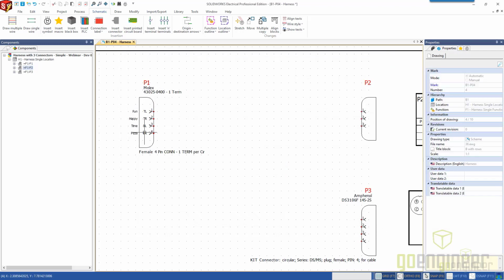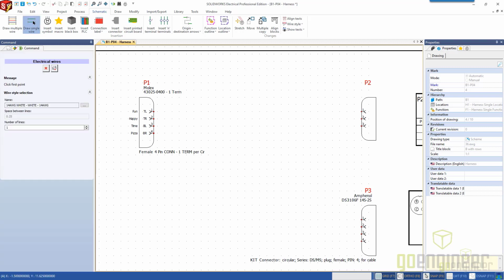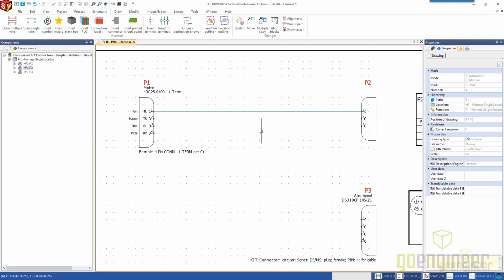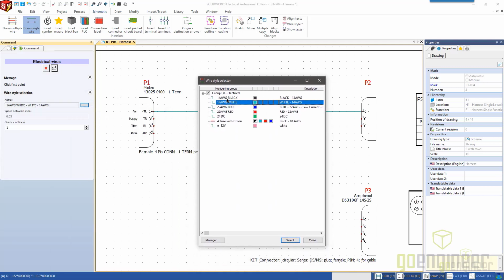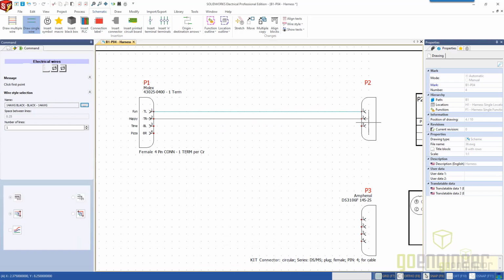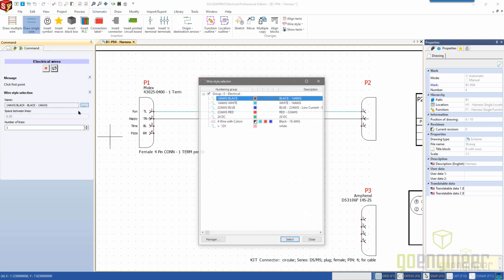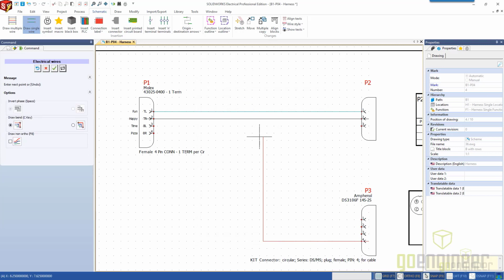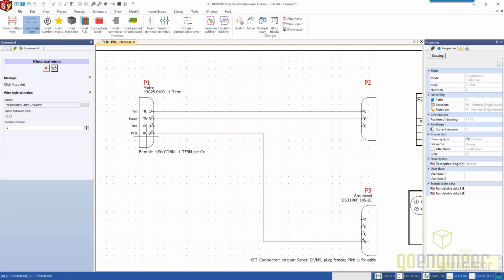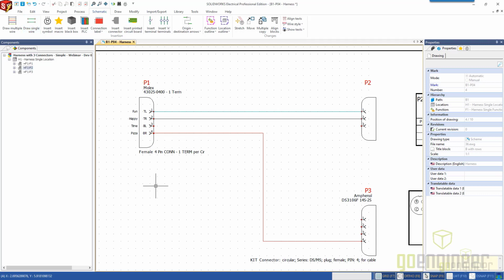Okay. All right, let's do some wires. I'm just going to do some real quick ones here. So there's my turquoise, just because I don't have a white wire that shows up well on white backgrounds. And I'll pick out some other colors here. So I'll do a black. And then also maybe come up from the bottom here with one of the other colors. Let's do red. So we'll come up and over. Notice I'm drawing into the connector. Once I right click one more time to get out, it does the trimming for me.